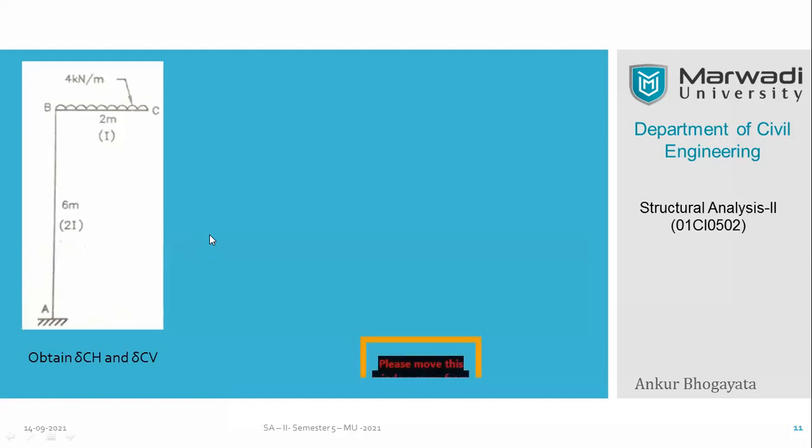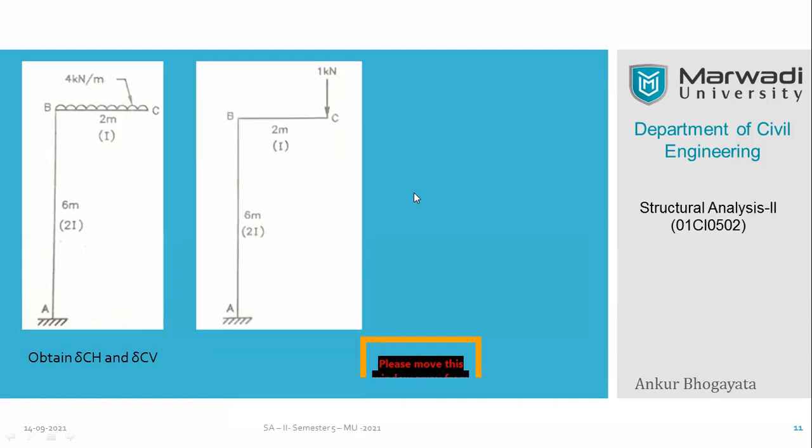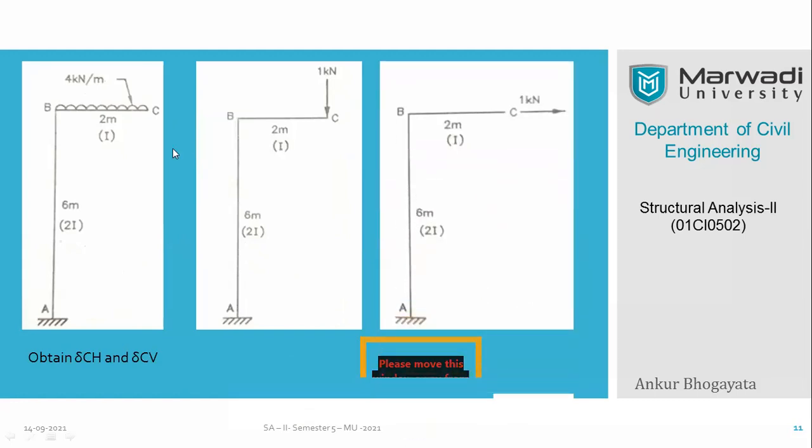Quickly, we will take this example. I insist, it is really very interesting. It is a bent frame. You can see here, let me describe some of the conditions, and I'll give you some tips also on what you have to do. The instruction is that you need to obtain the deflections only. There is no question regarding slopes, but deflection will be considered in two directions over here, vertical and horizontal. So we have a bent cantilever named A to B and B to C. So naturally we will have two segments, C to B and B to A.